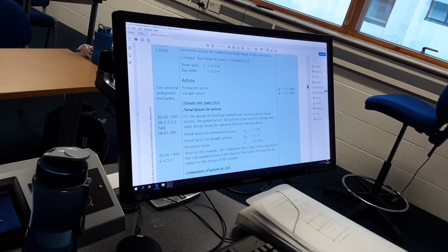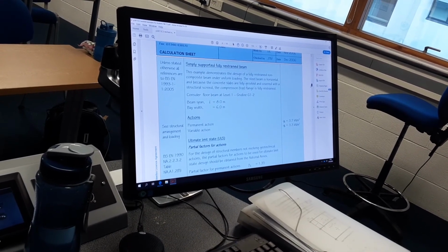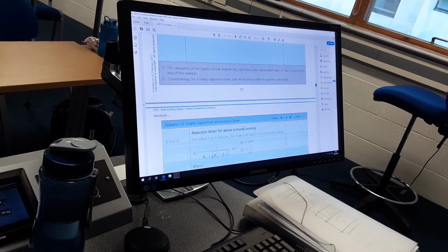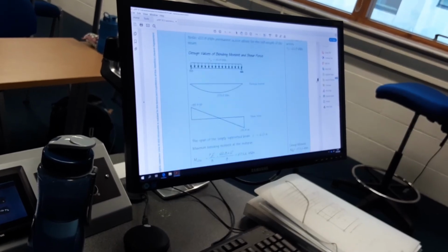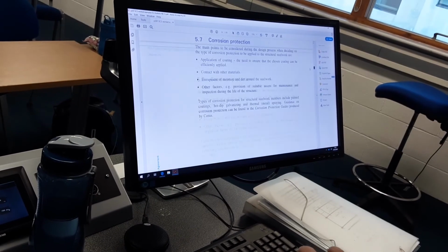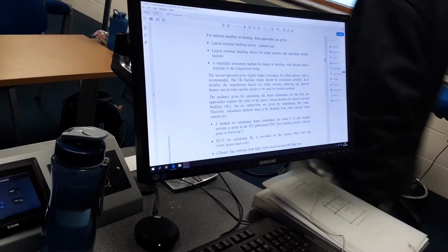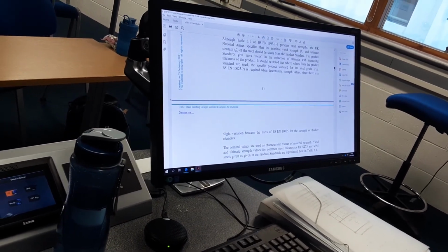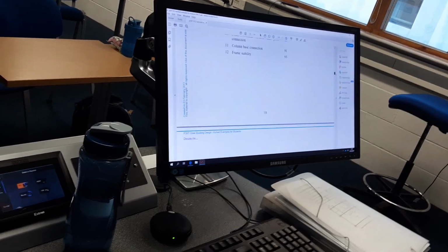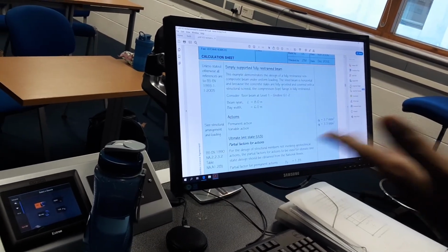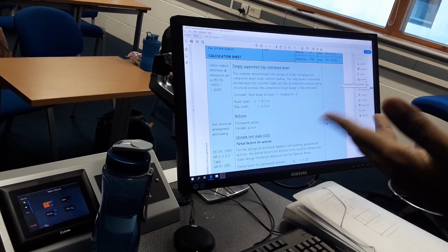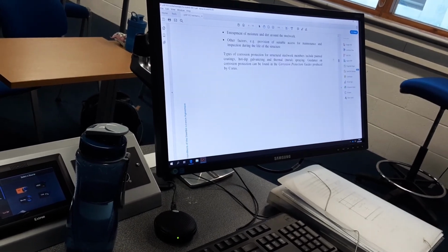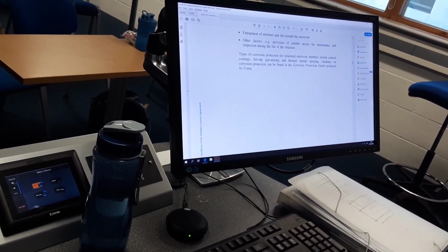So you design a primary beam as an unrestrained beam, and you design a secondary beam as a fully restrained beam, and also you have column design as well. So you have design of all those members. So follow this, but obviously your dimensions will be different from this. So you use it as a resource to see how to design the entire building. Okay. And obviously, I've covered quite a lot of topics in lectures as well, like compression members, beams, and so on. So this will follow the same kind of procedure, but in a building sense. Thank you.